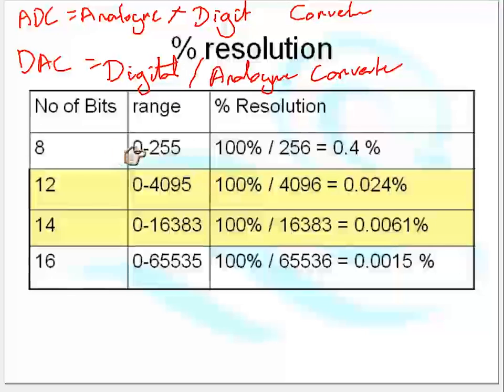Okay, an 8-bit ADC. In 8 bits we can store the numbers 0 through to 255. What that means is, with an 8-bit ADC, if you were outputting, for instance, to a valve, you would see that valve stepping open in steps of about 0.4, about 0.5%. So if you were inputting from a temperature sensor, you would see, as the temperature went up, the temperature jumping in half-degree increments, which isn't very accurate. If you want to read 12.12, you won't read 12.12. You'll read 12 and you'll read 12.4. And that's as accurate as you're going to get.